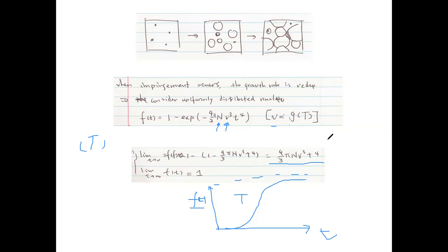Okay, so that's that. And another thing is, how generic is this mathematical equation? Because in deriving it, we assumed a very particular nucleation scenario. We assumed that nucleation can occur at a constant rate throughout the entire process. Now, in general, this may not be true, right? The nucleation may actually occur faster in the beginning and slower at the end, etc. So in practice, there's no guarantee that you're going to have exactly this scenario.